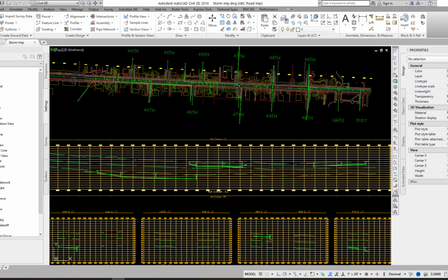For some unknown reason, a maximum number of 27 catchments can be transported from Civil 3D to SSA at the same time without creating significant errors. This may change in future releases of Civil 3D. Due to the limitation of transporting a maximum number of 27 catchments, it is recommended that pipe network groups be created in a manner to comply with this maximum number.